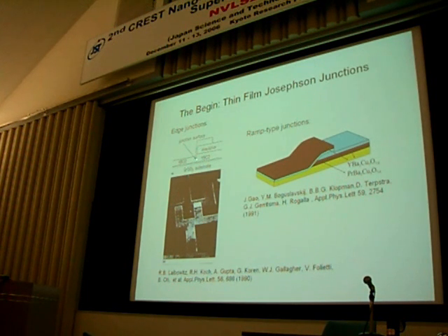At IBM, one worked on these steps where YBCO to YBCO connections were made via a material which was deposited across a step, and grain boundaries were coming up here at this step. So one had a nice coupling for YBCO to YBCO, again via grain boundaries. But this wasn't very well developed, and we thought at that time, why not make this angle here very flat, to something of the order of 20-25 degrees? Because in that case, you can have epitaxy all through the sandwich.